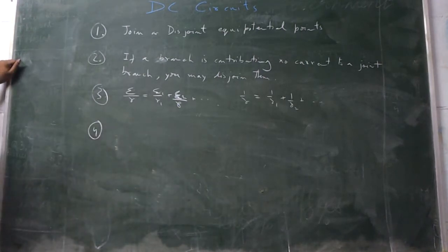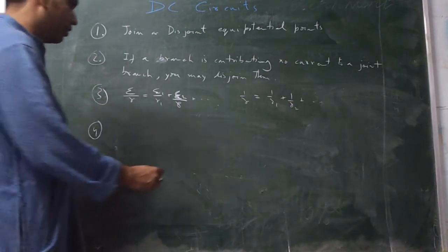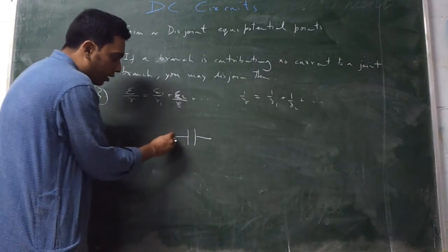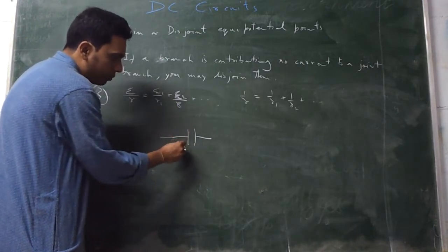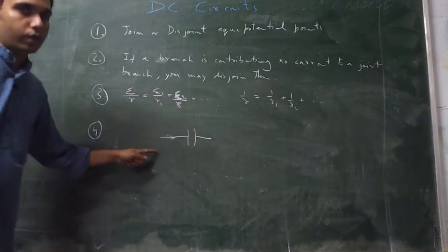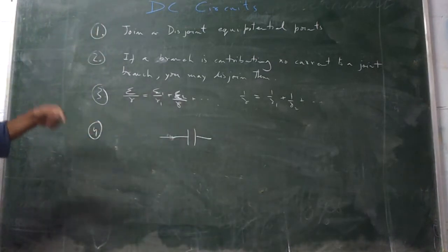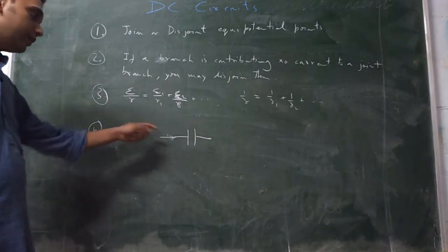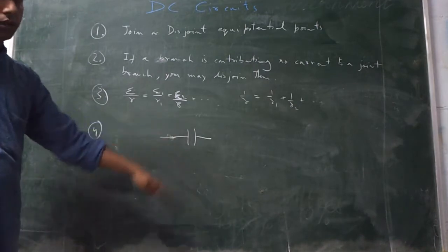Okay, now we'll go on to the capacitance. Circuits involving capacitance. So you have to have a clear idea that if you have a capacitor in a circuit, first of all, the current, the source which is charging the capacitor, the current has to go through a resistance. If there is no resistance in the path, the capacitor will get charged instantaneously. Then you don't have a charging and discharging formula for that. It charges instantaneously if there is no resistance.